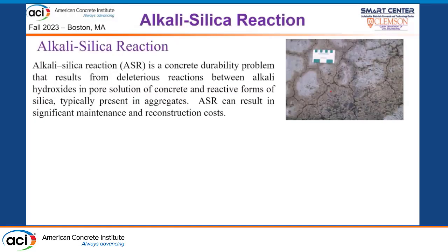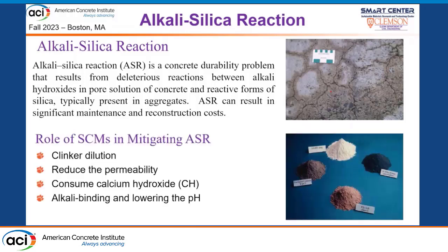The ASR is a concrete durability problem that results from the deleterious reaction between alkali hydroxide in the concrete pore solution and the reactive forms of silica typically present in the aggregates. This reaction results in significant maintenance and reconstruction costs. The most effective way of mitigating the ASR is to use SCMs.